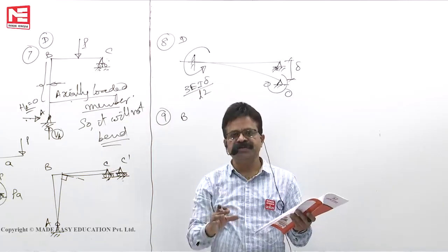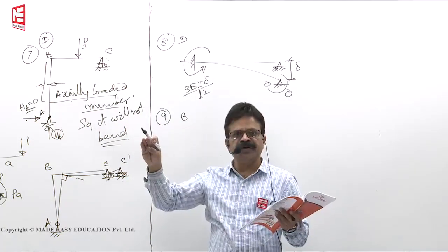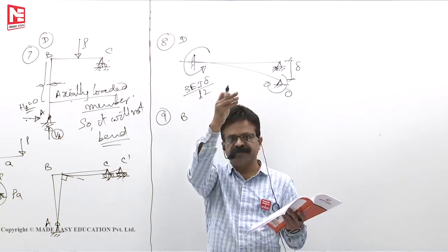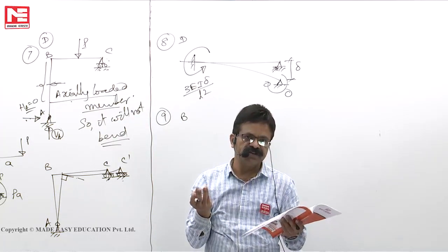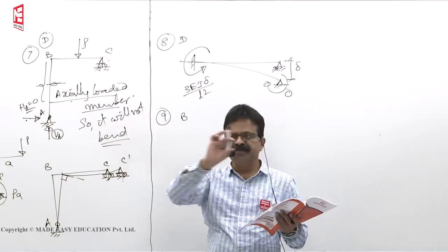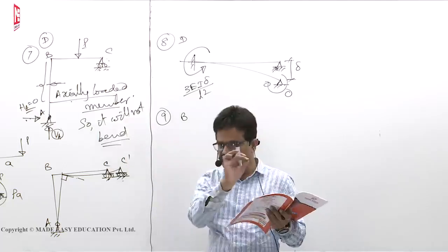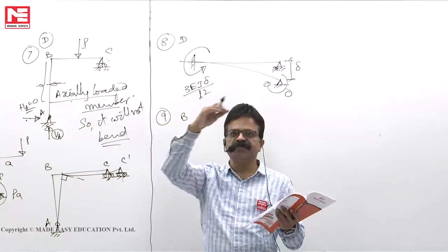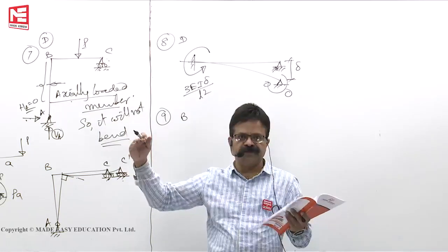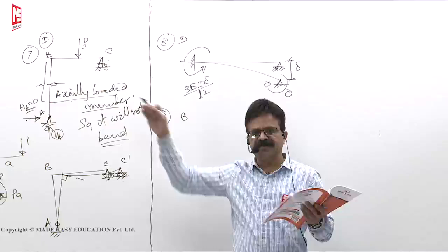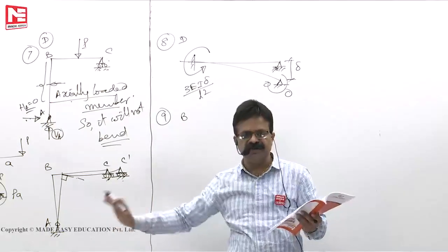If you have a multi-storied frame, say, any beam when you want to analyze, below the beam you will fix it, above the beam you fix it, because anyhow it is not swaying. So where the sway is not there, you will take only a substitute frame. Means only one beam, continuous beam, and columns you will take. Assuming that above the floor all columns are fixed, below the beam all columns are fixed.